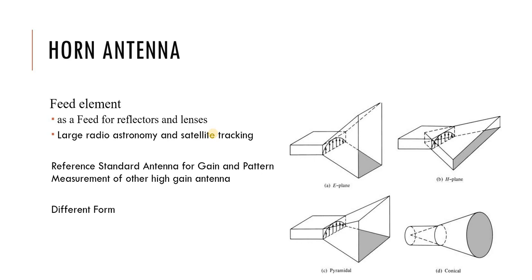For example, as you can see in picture A, the E-plane sectoral horn has its opening flared in the direction of the E field, and they call it the E-plane opening, while B is the H-plane opening. That's the naming for this antenna. And the aperture field, as you can see in the picture, is tapered to the large opening, and this large opening can radiate the electromagnetic field into free space, and you can shape and manage the field through this tapering. And let's go to HFSS and see how to design it.